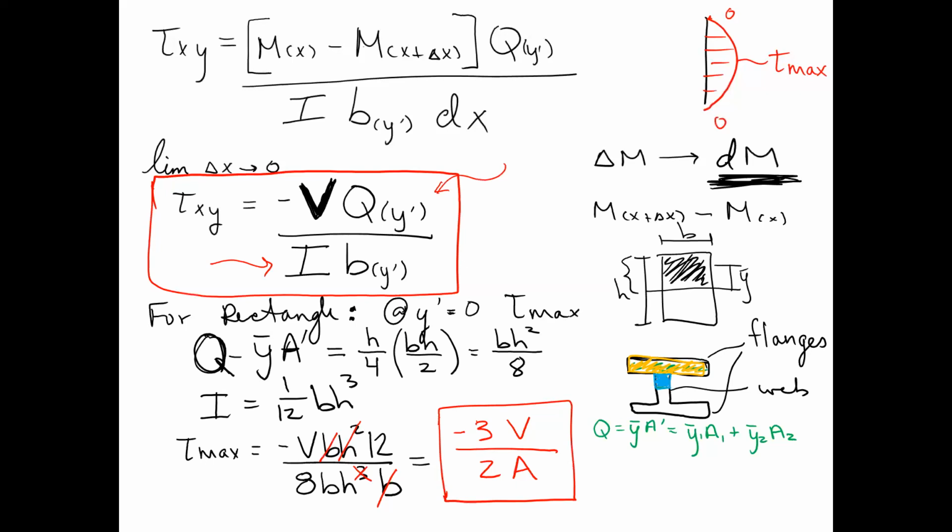When you're calculating these, if your measurement Y is up above the centroidal plane, that's a positive value of Y bar. If the Y bar measurement requires you to go down below the centroid, that's a negative measurement. So you can get negative Ys. That's how it ends up decreasing as you go down below, because you start having a negative Y.